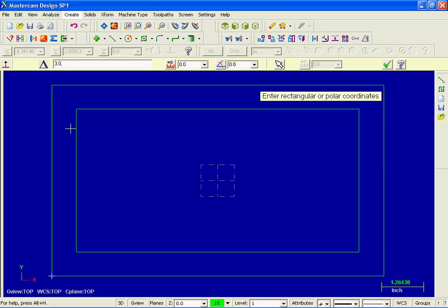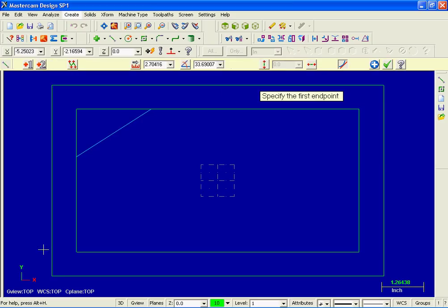Now the y value from this lower left corner: looking over on the left hand side of the drawing, there are three vertical dimensions that I'm going to use. The first one, 0.75 plus 3.0 plus 1.5, and I'm going to hit enter, and there's my first line.